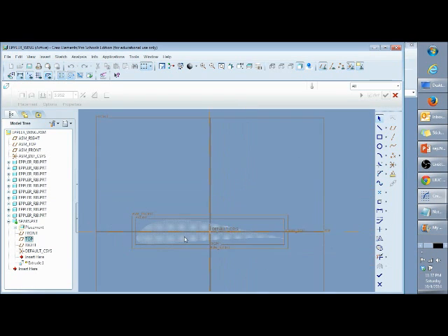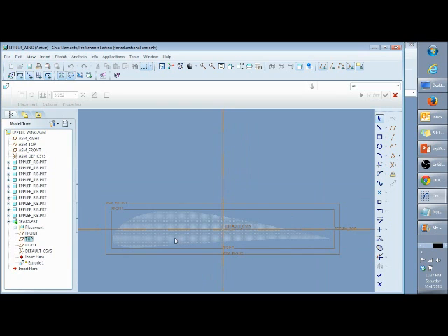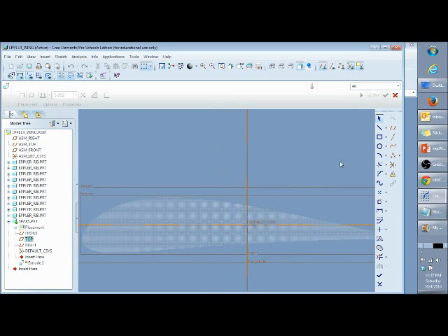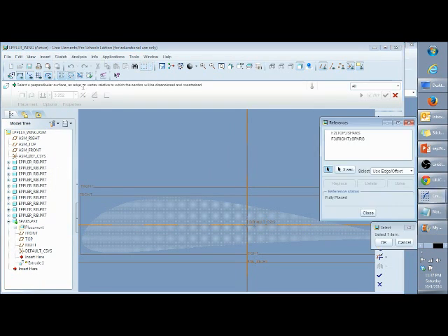So what I want to do now is create the spars. I'm going to make my spars about 1/8 thick. What I want to do now is set up references. Just go to Sketch, References. If you're within Creo, go to the Sketch tab, and there should be a little button over here that says References.